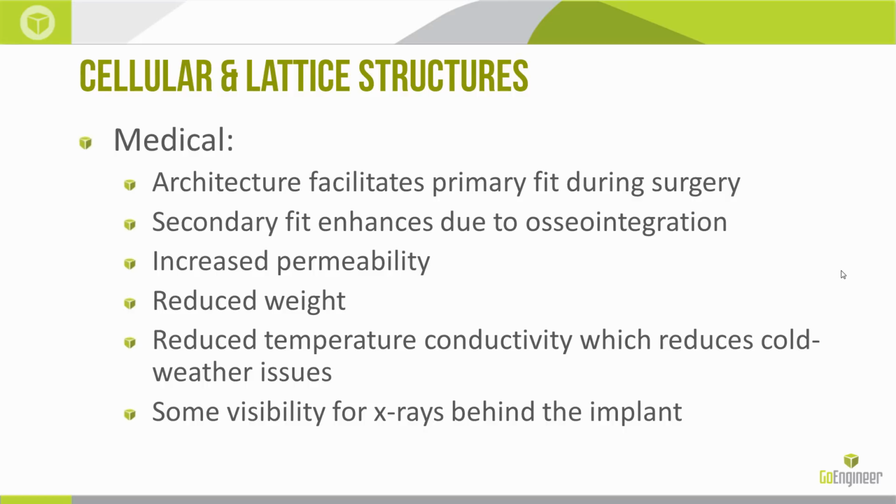And we can design parts, going back to how these shapes are created, we design these parts, say, from CT scans. You know, getting a 3D printed part or an STL file from a CT scan is now a very tried and true technology. There's open source software out there that can take your CT scan, take the images, stack them up, and build an STL file for free. And it's done within minutes.